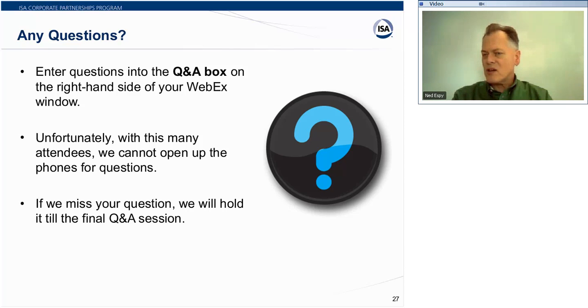So your calibrator is traceable to some standard, and you're comparing that traceable measurement to what the field device, in this case the level transmitter, is measuring. And if they're off, you need to adjust them. And somebody's asked a question here about making an adjustment. We are going to demonstrate an adjustment on the next calibration that Roy does. So we'll actually go through that and you'll see it.